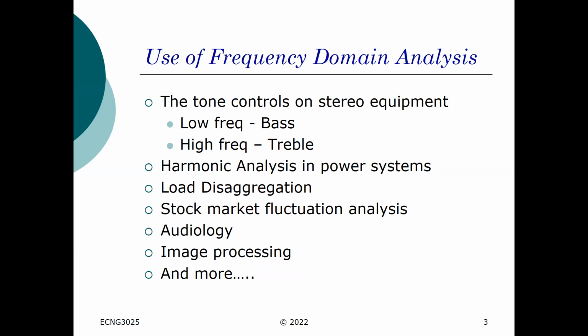The power systems, people do this a lot because harmonics represent a source of wasted energy. So if you have a system that is supposed to be a 60 hertz or 50 hertz system, but in the course of either generating that or using it, you are generating, like if it's a 60 hertz system and you're generating 120 hertz or 180 hertz on top of the 60 hertz, what you have is wasted energy there. Okay, so it's very critical in that regard.